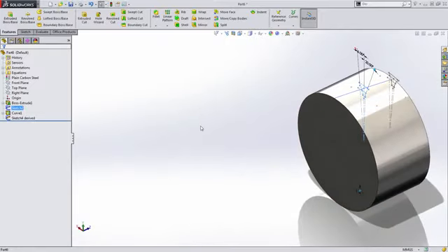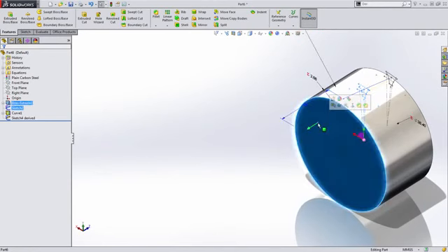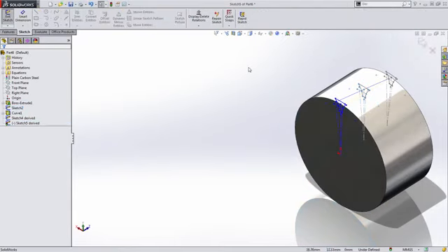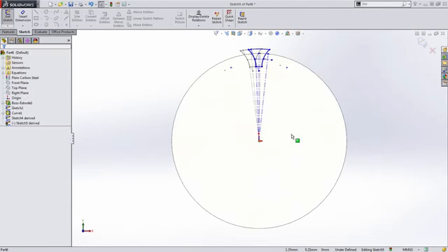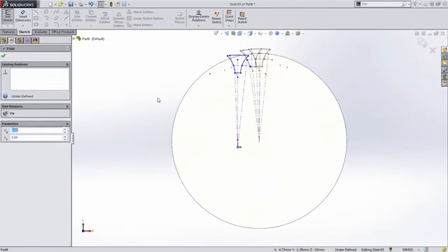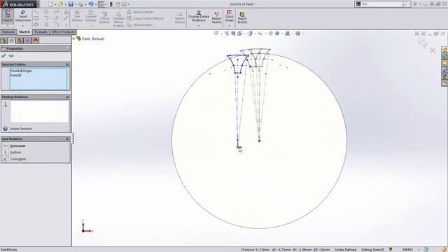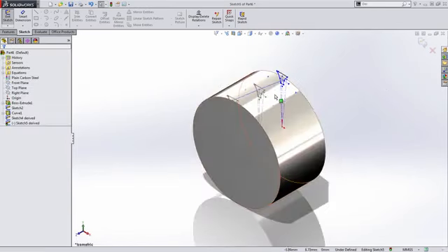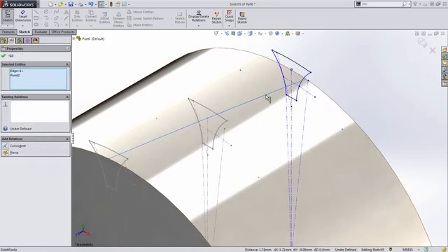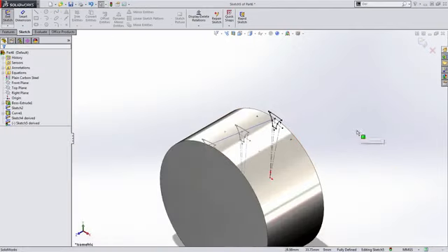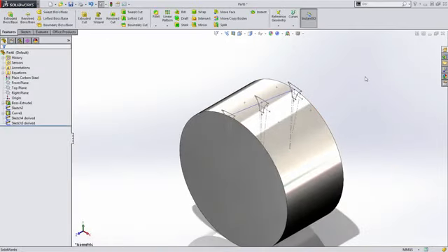Again, we're going to pre-select our original sketch. We're going to pre-select the back face, and because derived sketch was the last thing we searched for in command search, I can just simply click the spyglass and choose it again. Now again, I'm going to simply snap this onto the center, and it doesn't look like I got it. If you have trouble with this, you can always pre-select the origin in this point and choose coincident. And then like before, I'm going to select this common point, and holding control, choose the projected curve and add a pierce relationship. I'm then going to exit the sketch.